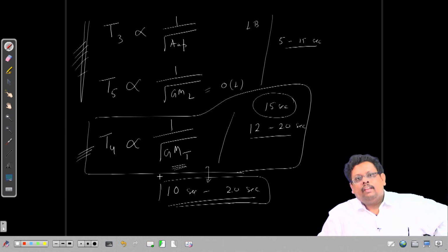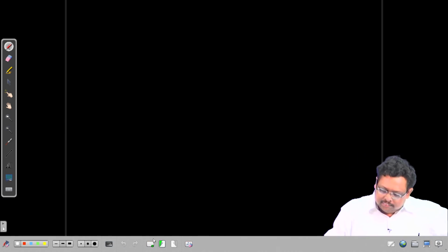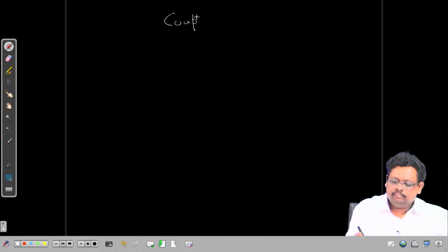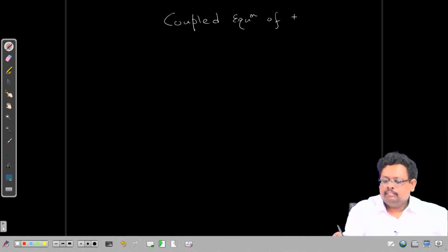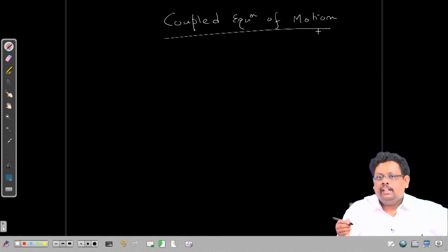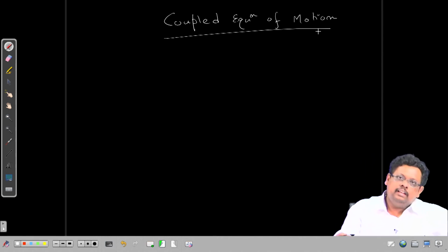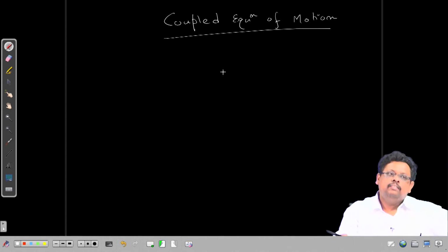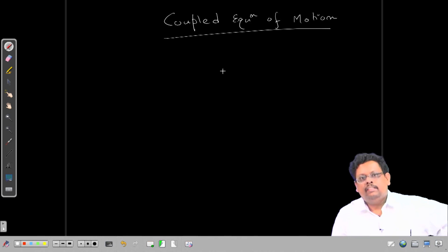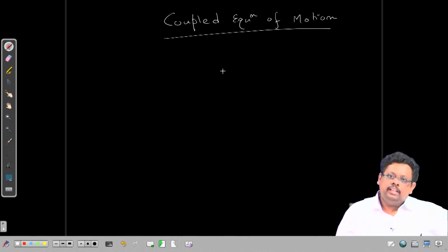Okay. So, this is more or less what I am going to discuss today about the heave, pitch and roll. And now, let us start something on the coupled equation of motion. Now, again one more concept is the encounter frequency, and we are not discussing it right now. When we discuss the forward speed problem, at that time we will come back and discuss something on the encounter frequency. Here we assume that the vessel does not move forward, it is floating.